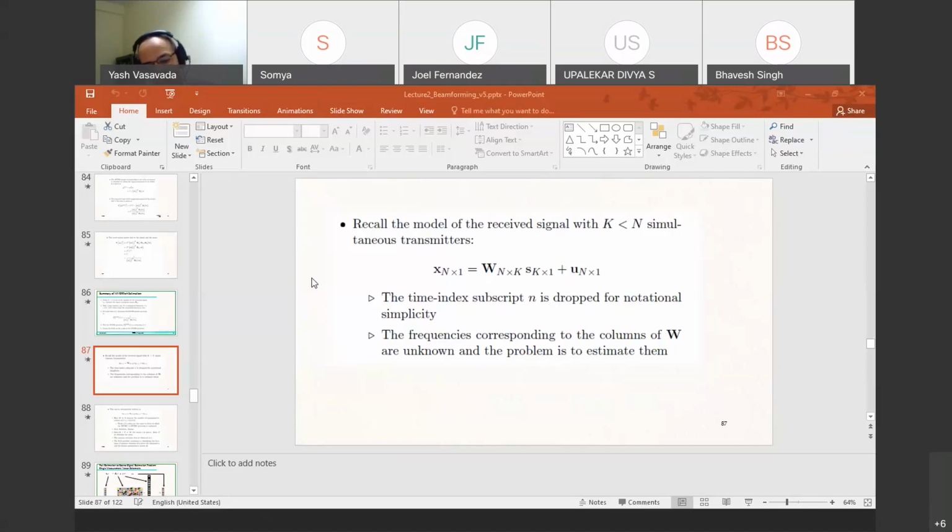And the consequence of that is that each of these eigenvectors corresponding to what is known as the noise subspace, that vector is perpendicular to the incoming signal vector. And so the MUSIC algorithm leverages that property of EVD. It scans the entire frequency spectrum, and for each frequency, it forms a dot product with all of the eigenvectors corresponding to the noise subspace.